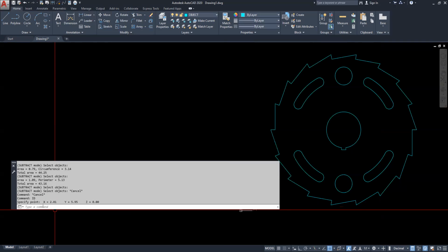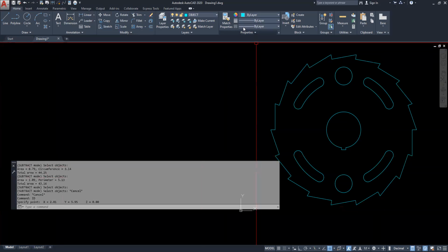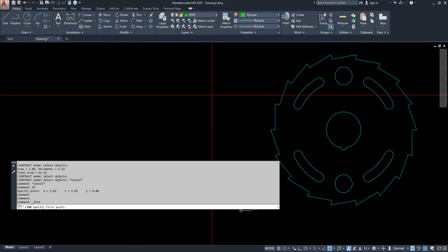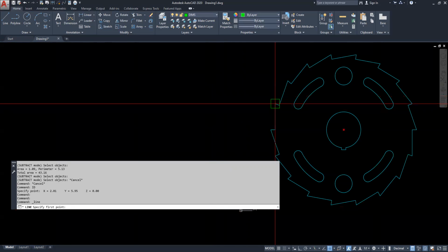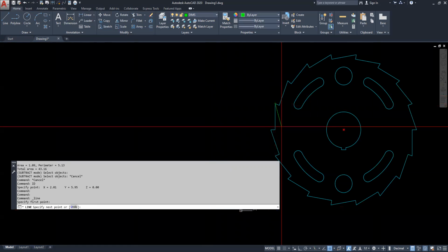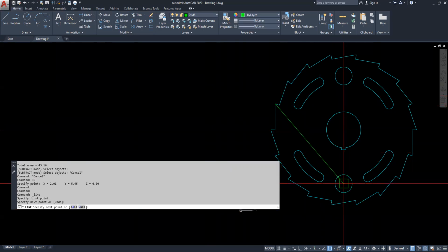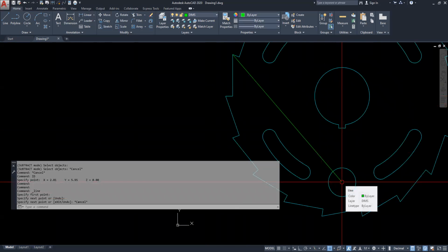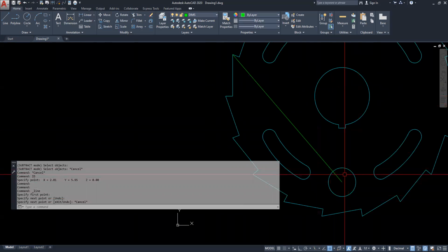And the last question, the angle formed in the XY plane from the endpoint at line C. So I'm going to go on to a different color on the DIMS layer. The endpoint at C is here to the center of the one diameter hole at D, to the center right here. So when they say center, they mean like if you were drawing this by hand, that's where you put the needle of the compass to draw the circle around.